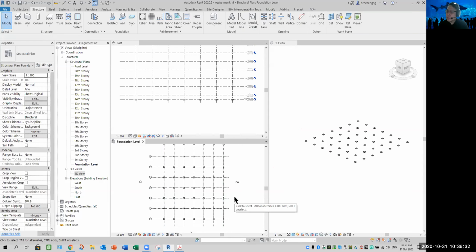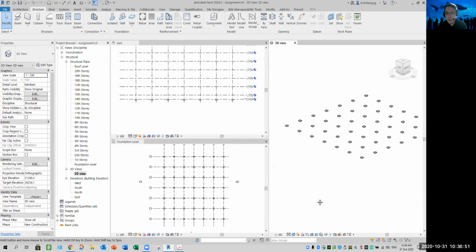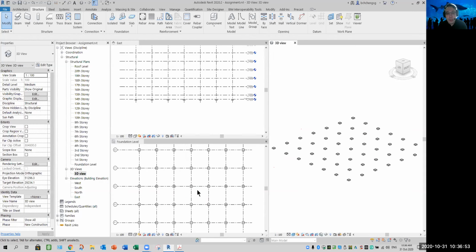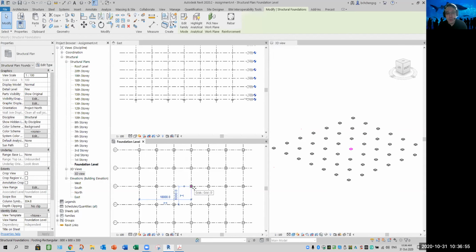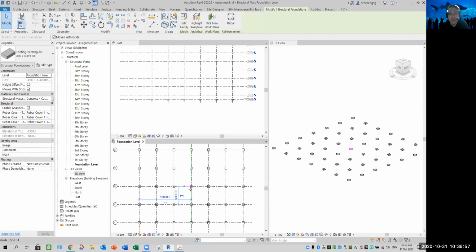In Revit, 2 rules. When you need to model, you model. Don't often click undo. Model wrongly, never mind. We can swap. For instance, now, let's say this particular part of this footing here, the middle one, I want to change to a different one. Notice when I select them, my properties type selector is highlighted.